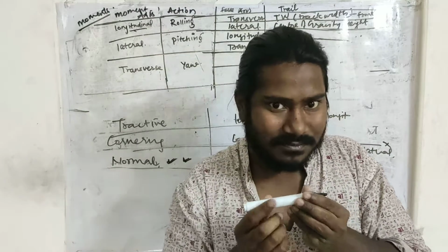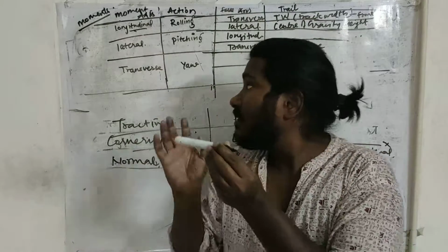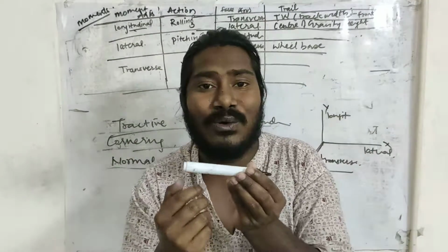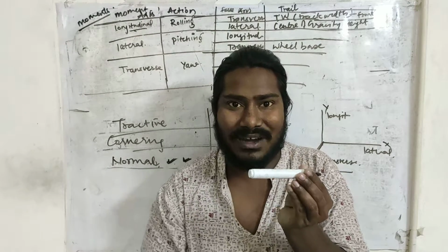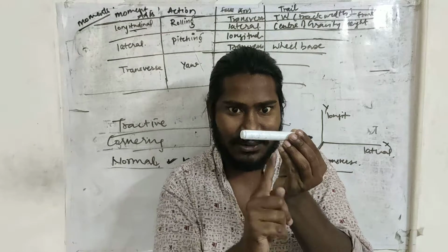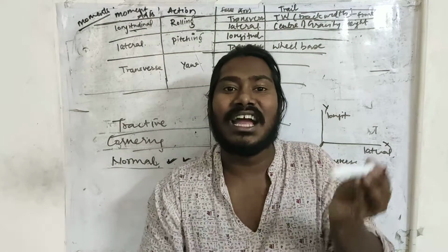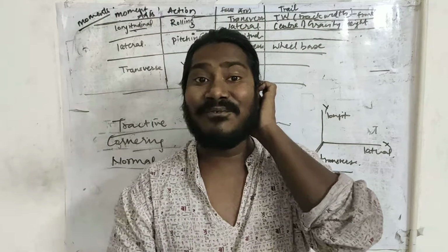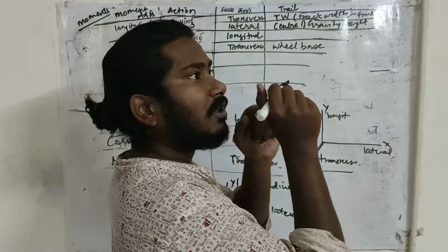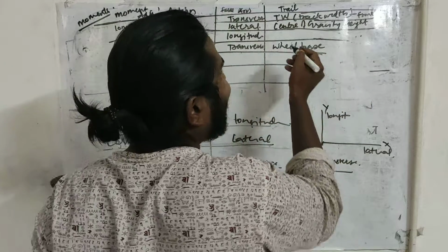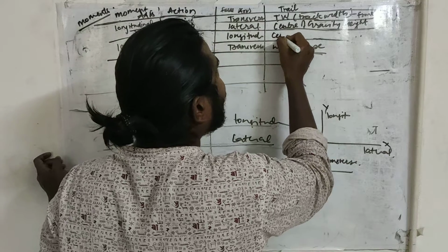Center of gravity, right? Along the longitudinal axis, either the inertial forces, the D'Alembert forces, are acting, or the tractive forces at the ground are acting. The tractive forces at the ground act with the height of the center of gravity. Whenever I talk about the longitudinal, it is about the tractive forces or the inertial forces. Inertial forces are acting at the same position, so we won't consider them. So we will be considering the tractive forces at the ground, with the height of center of gravity.